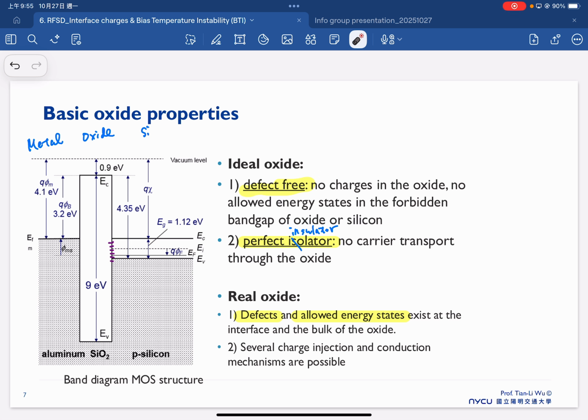If you don't fully follow the idea of the energy state, then you should go back to look at semiconductor physics and devices. In the chapter where we talk about Schottky contacts, when we put the metal and the semiconductor together, we already talked about there being a state in between, because your silicon crystal stops growing in that region, and therefore there is a certain discontinuity layer, and this discontinuity layer in the end creates the allowed energy state.